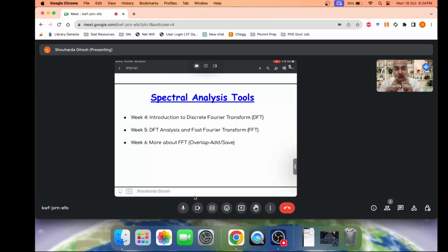Now you understand that these batches are discrete, but when you want to take the overall FFT, these two batches have some kind of connection with one another. You're taking each of these batches' individual transforms, but when you want to see the overall transform, there must be some combination between them. So in order to account for that, we use the overlap add and overlap save mechanisms.